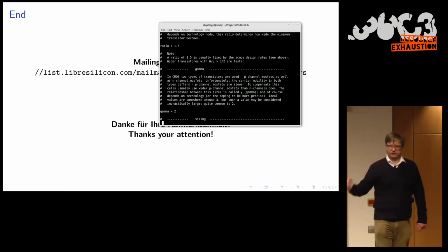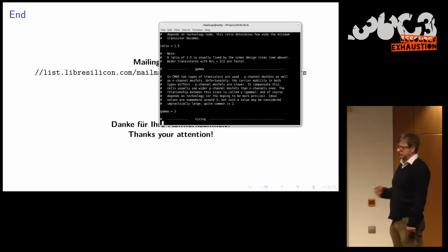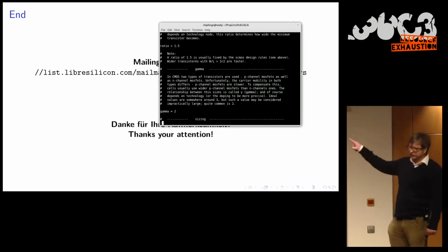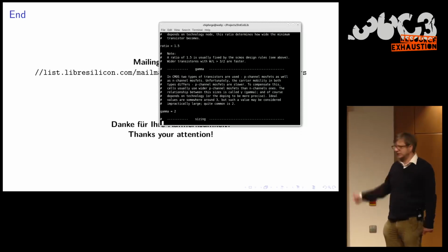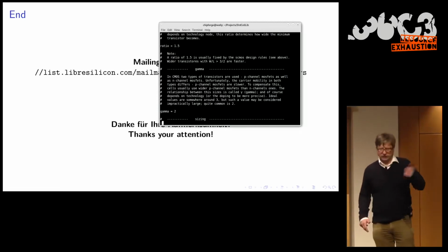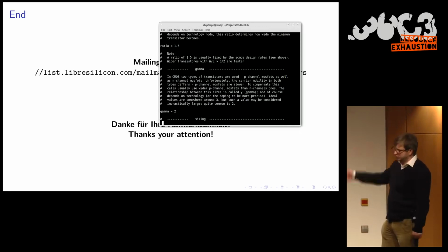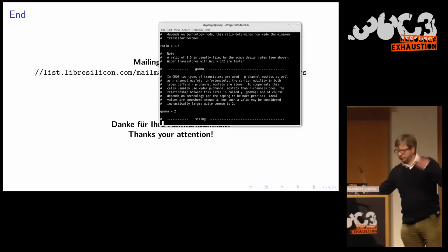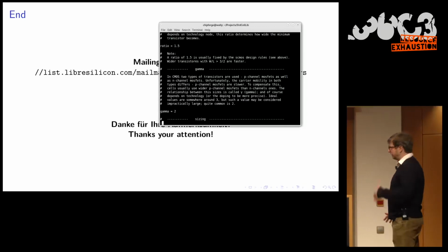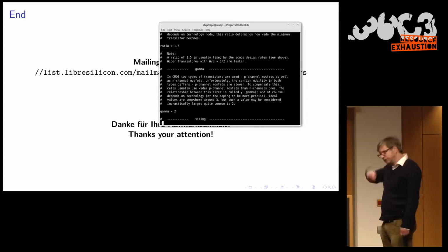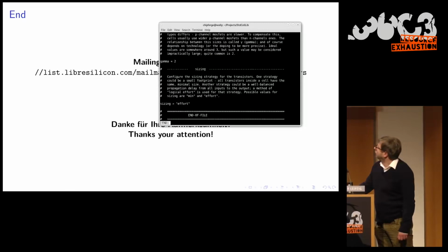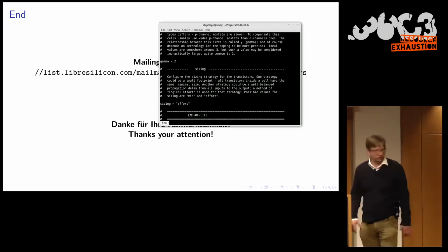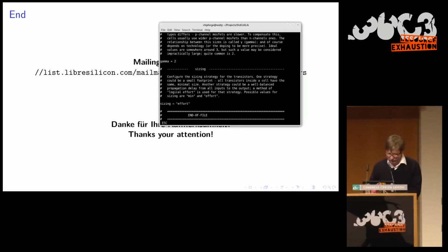So you make the p-channel bigger, and the ratio of how much bigger the p-channel is usually defined as gamma. I added a value which works well for many cases, but it depends really on the silicon. It's usually between 2 and 3 somewhere. So if I want something which is resistant to side channel attacks, then it's important to balance the value gamma.